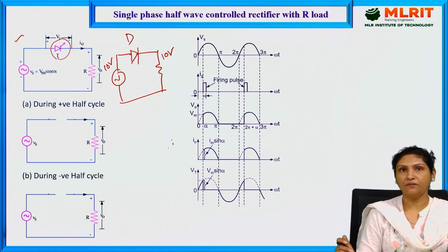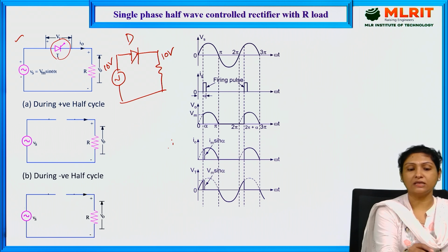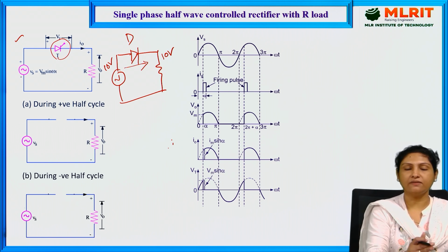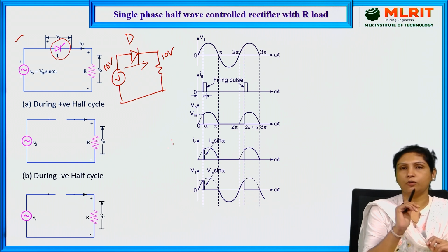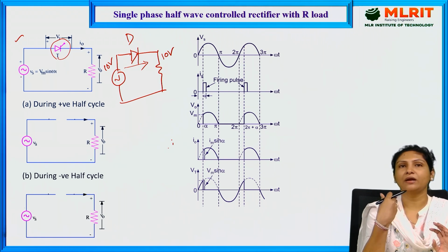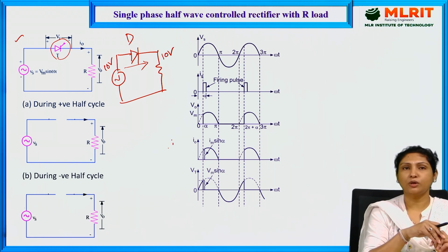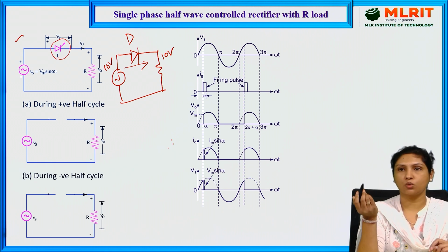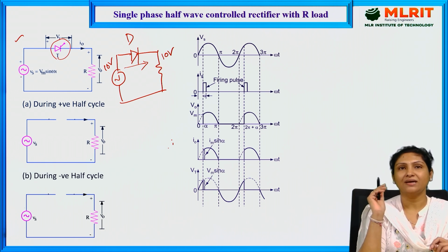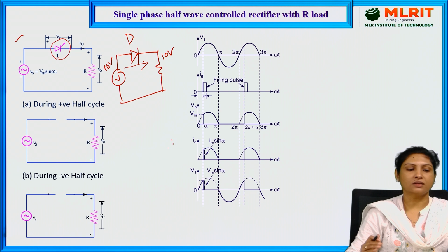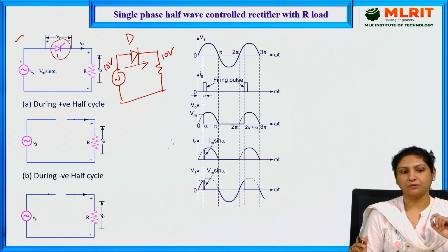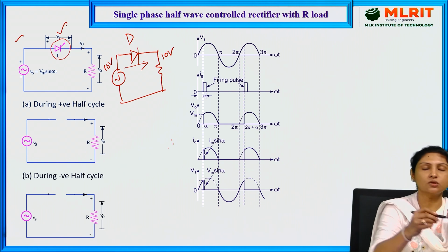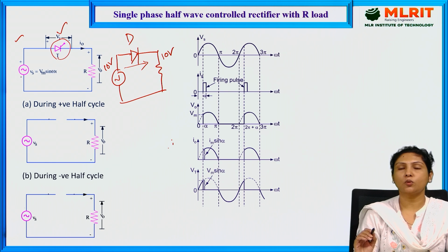If we make use of a diode, once it is forward biased and starts conducting, it gives the same amount of output voltage as whatever we have applied as the input, because a diode has no control over the output voltage. In this scenario, the thyristor came into the picture, and the whole purpose of the thyristor is to provide control over the output voltage to the load.